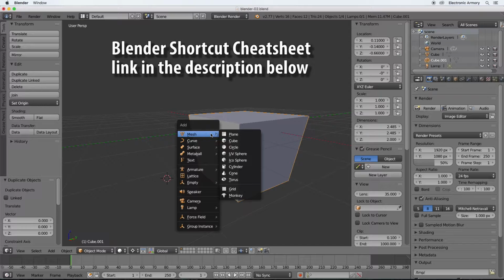If you forget a keyboard shortcut, each view, say the 3D view, has a bunch of menus attached to them. Scan through these for different actions you can take, and they'll list their shortcut for each menu item. Some share the same keyboard shortcut. In those cases, that usually means that shortcuts bring up a menu with those items in it. In this case, an add menu appeared with multiple objects in there.